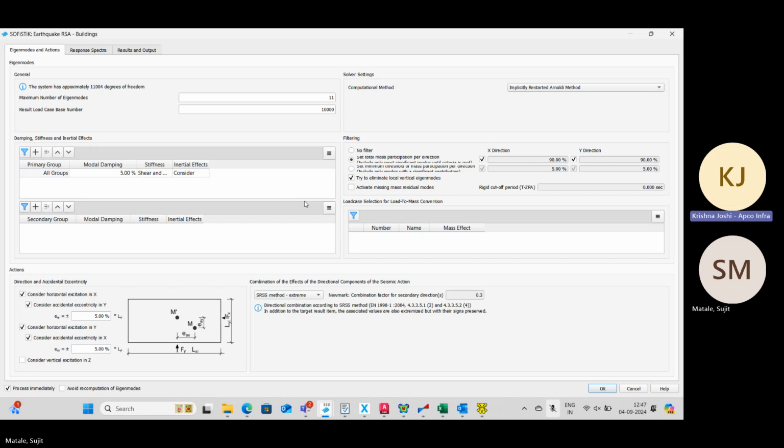It is always a good idea to run that particular response spectrum analysis on one single small column, and look at your manual results and results as per the response spectrum analysis. Right? So, this is the other way. Cracked stiffness 0.75 here. How do you calculate? Can you calculate the crack stiffness also in this one? That's a very good question.